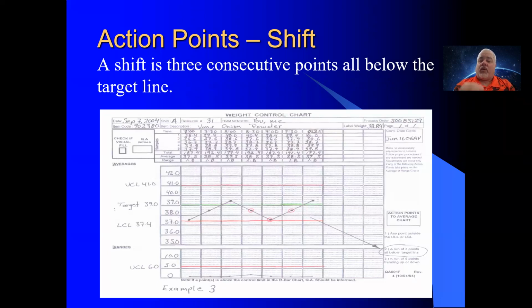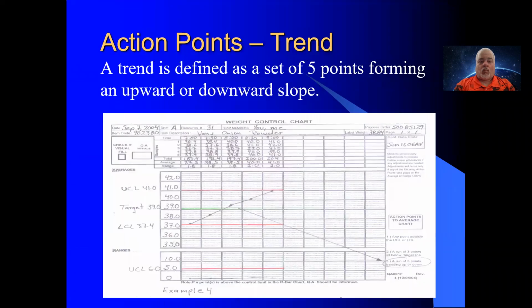We got to make sure that we don't have the entire run below weight. Now keep in mind there's a little bit of cushion because the target fill weight is slightly above the label weight. So there's a little bit of room for cushion. And each company has to decide how much above the label weight is our ideal sweet spot to put our target fill weight.